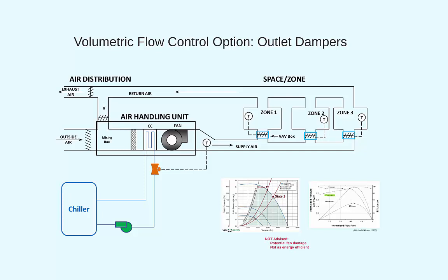So oftentimes these systems have another damper located just downstream of the fan, back in the mechanical room. If the VAV dampers start to close, this will drive up the pressure in the supply ductwork. We can place a differential pressure sensor in that supply ductwork. Now, this is often referred to as the static pressure sensor, but what it is really doing is sensing the difference in static pressure between the inside of the duct and the outside of the duct, which would be representative of the internal pressure of the building.